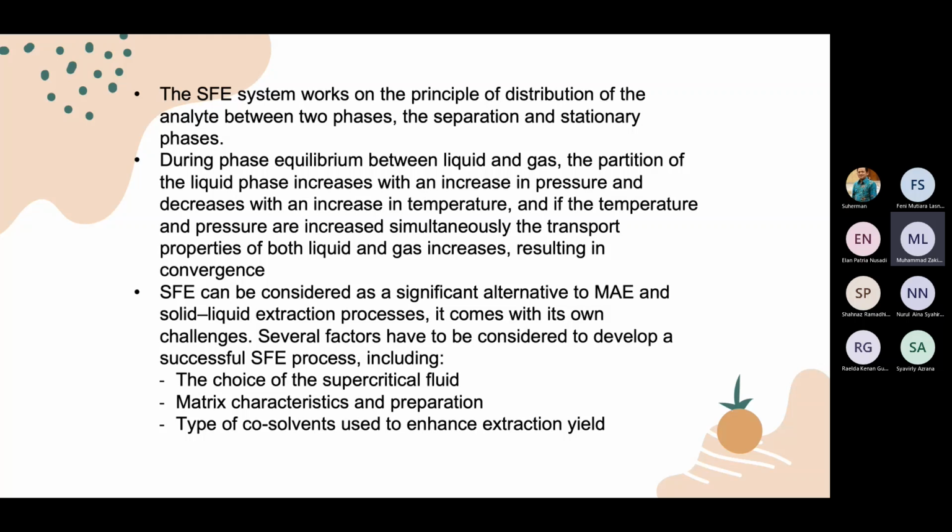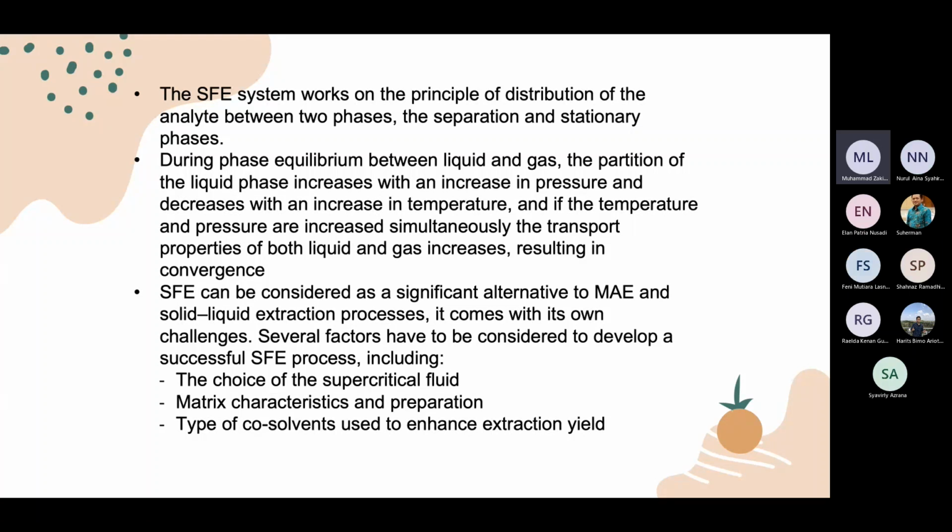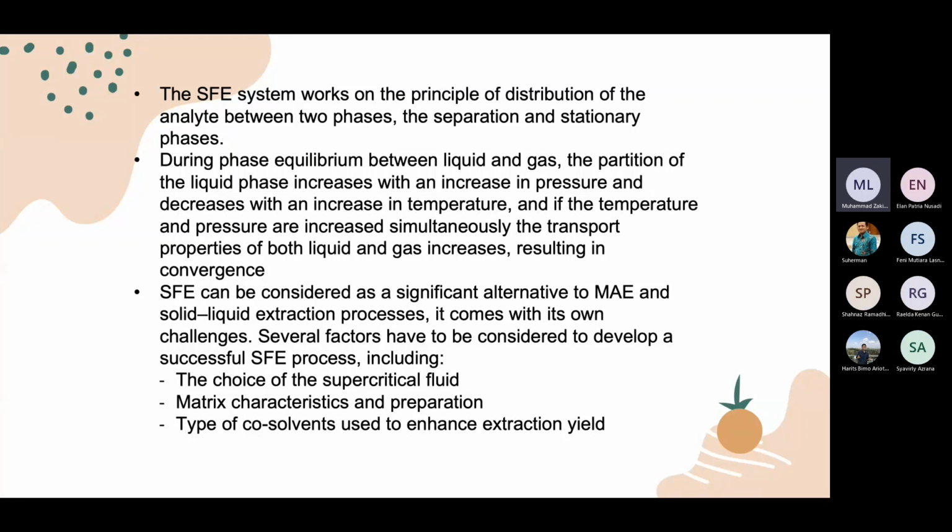During the equilibrium phase between liquid and gas, the partition of the liquid phase increases with an increase in pressure and decreases with an increase in temperature. And if the temperature and pressure are increased simultaneously, the transport properties of both liquid and gas also increase, resulting in convergence. SFE can be considered as a significant alternative to MAE and solid liquid extraction processes.